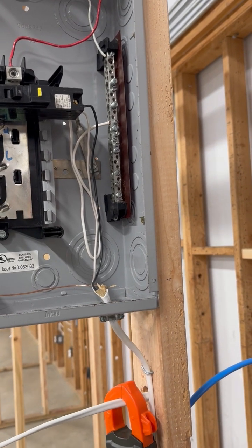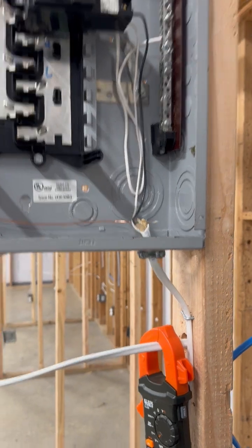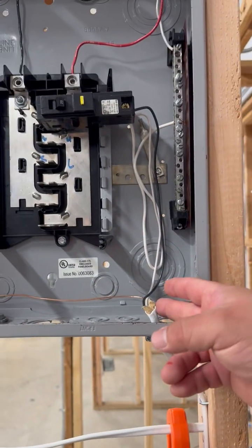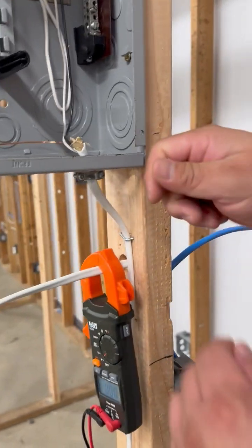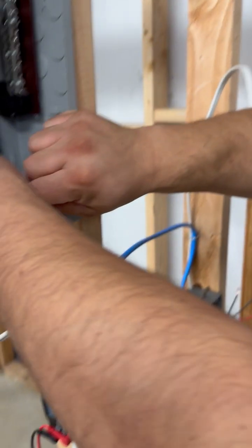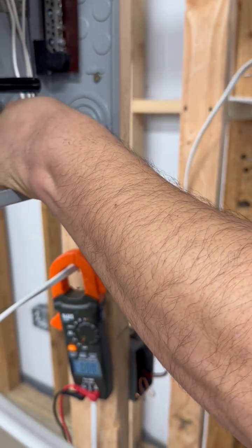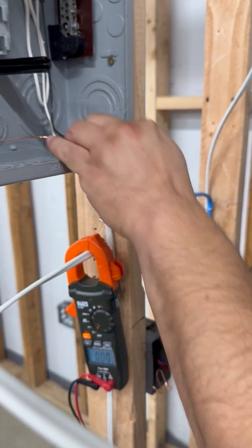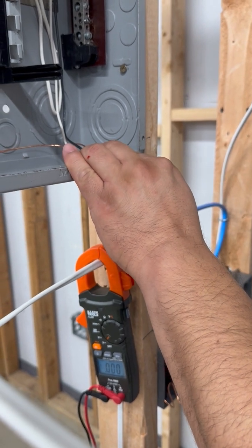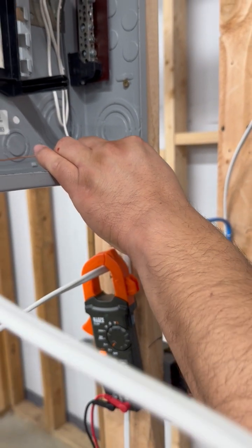If I see anything that looks dangerous, for example, I've seen this with a lot of students recently: when they cut this outer jacket, they've seen videos online where they take the utility knife and swipe this way on the front, swipe this way in the back, and rip it off. Well, I always tell them, the sharpness of that utility knife endangers a cut to the insulation on our inner conductors.